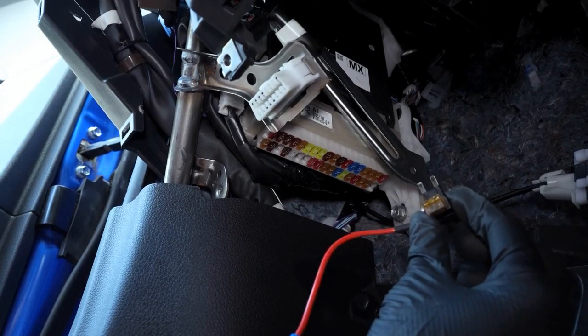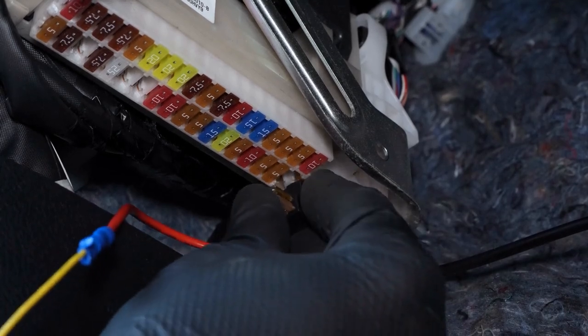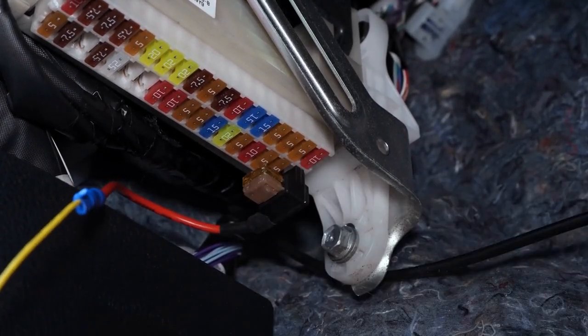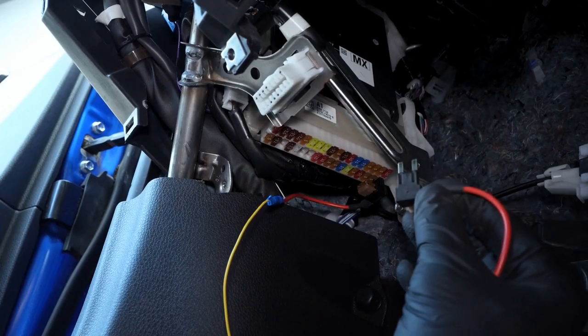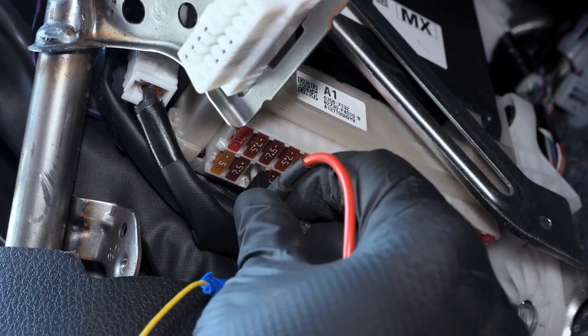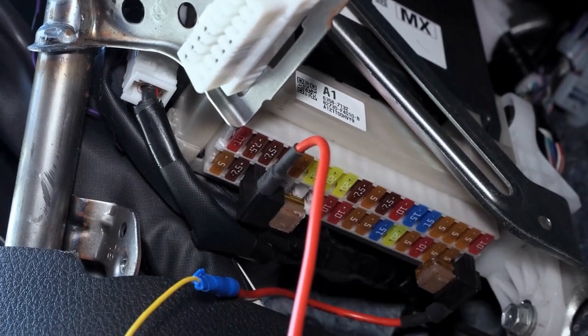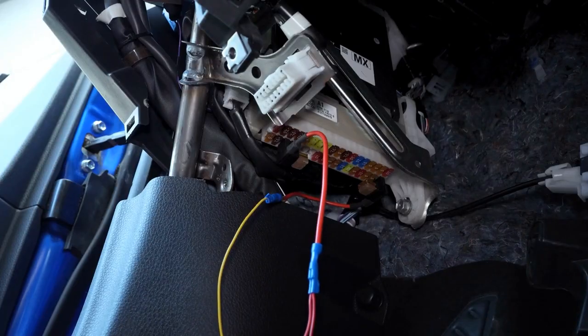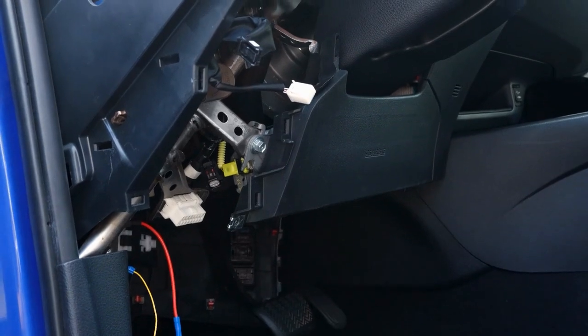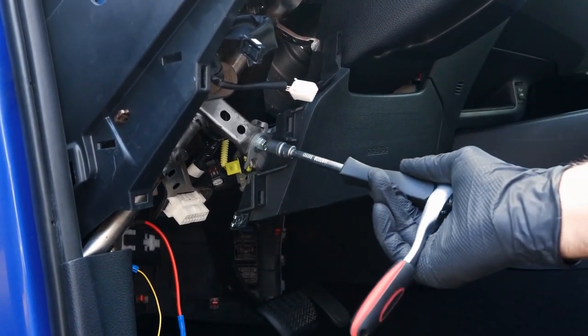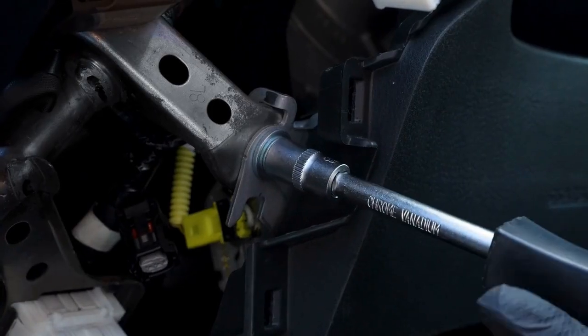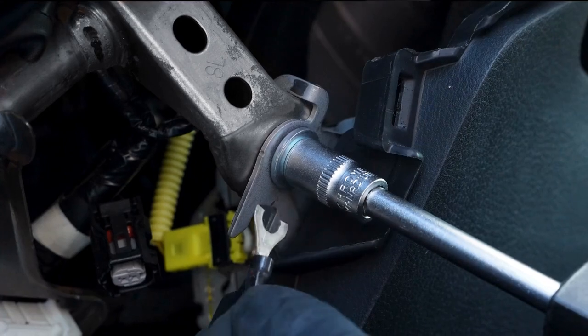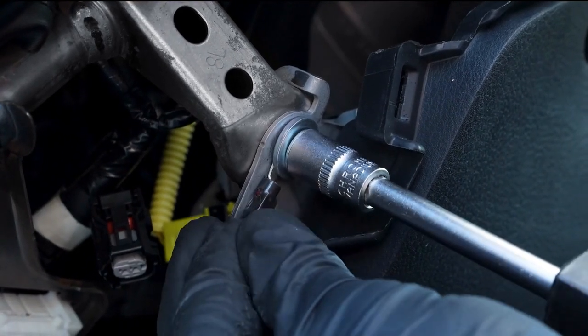Connect the prepared VCC and digital input wires to the vehicle's fuse box. Attach the U-type ground connector to the vehicle's frame to ensure proper grounding.